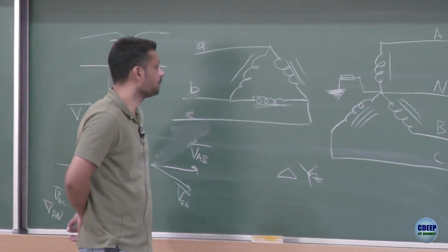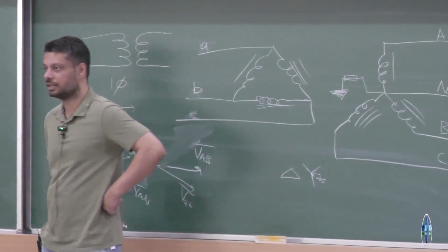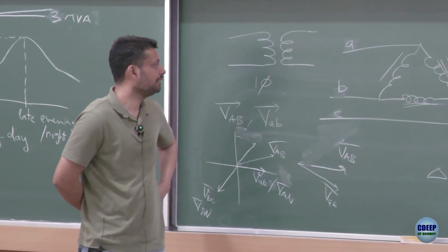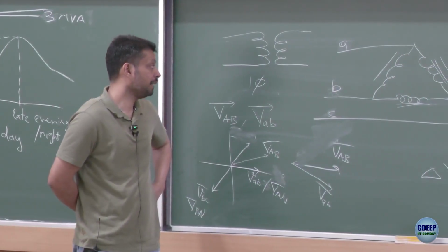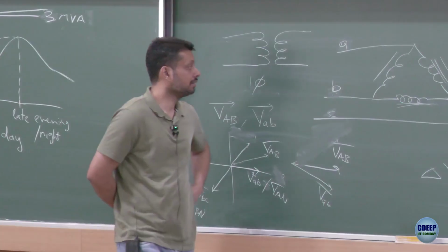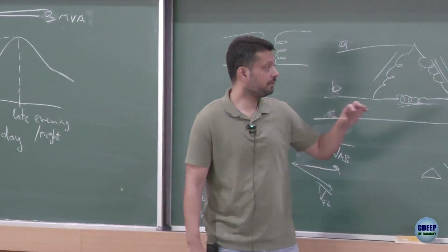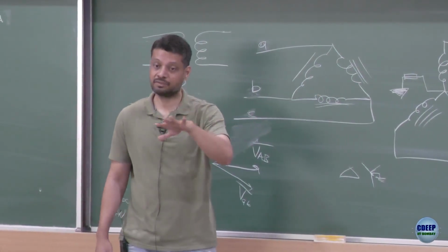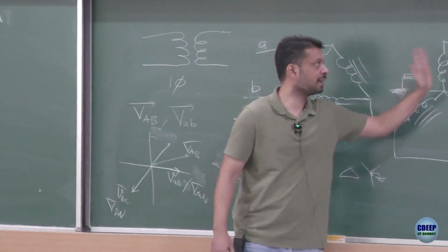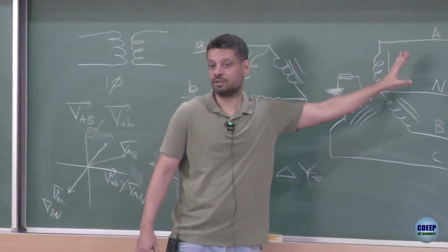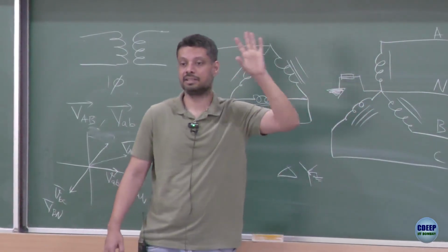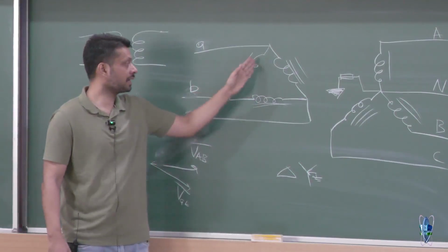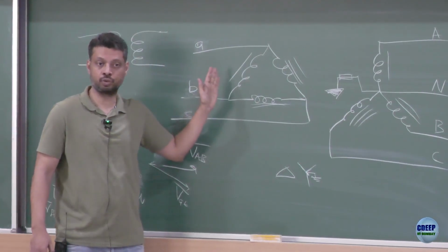Okay, so I am also not very sure, I have not really thought about it, but my very wild guess here would be that, first of all, this is something which is not covered in the course, but if you have a negative sequence component or a third harmonic current flowing here, let us say this A and N goes to a rectifier, there is a third harmonic current which flows there. If you have delta here, the third harmonic current circulates and it does not come from the source.